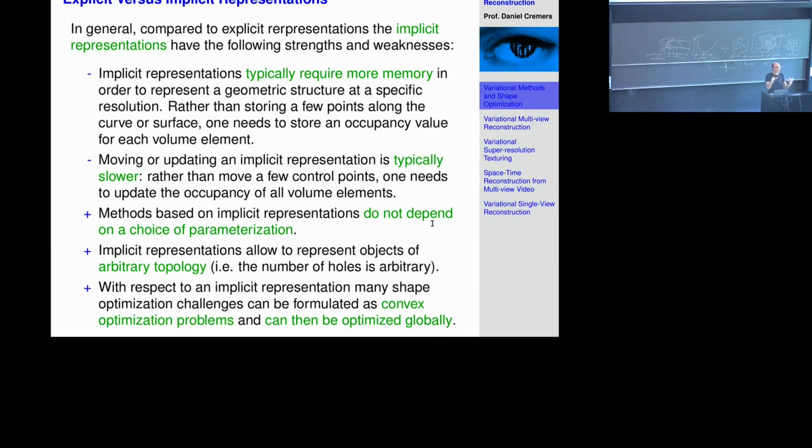How do you compare two different objects? You cannot just compare the spline control point vector, because it will not possibly be the same one. Even though you're looking at exactly the same object, you don't see that it's the same object if you use this vector of control point coordinates, and you might have two completely different vectors that encode the same object.